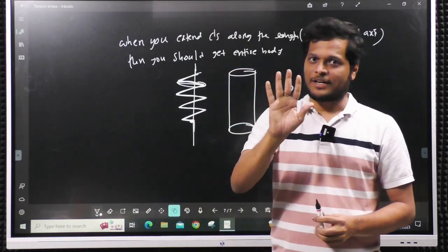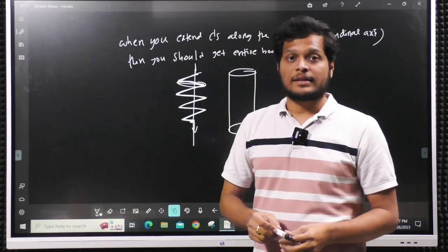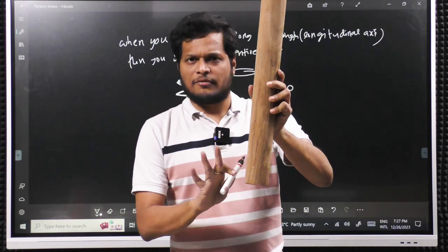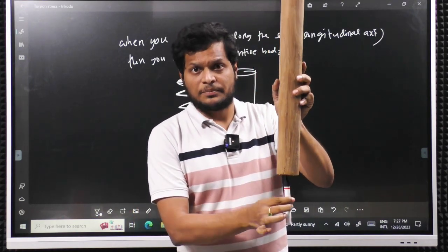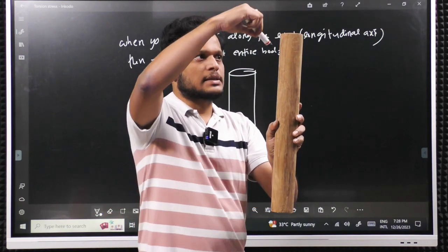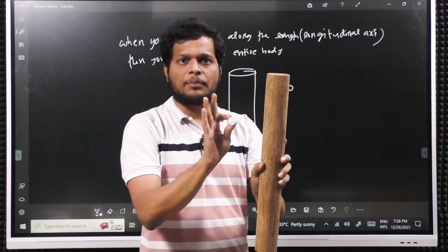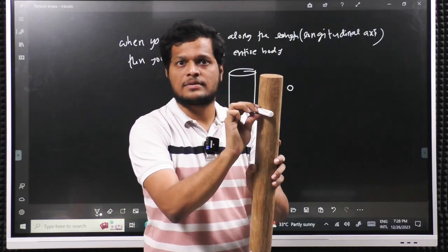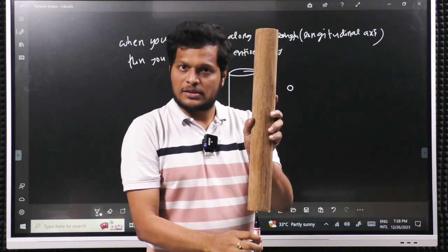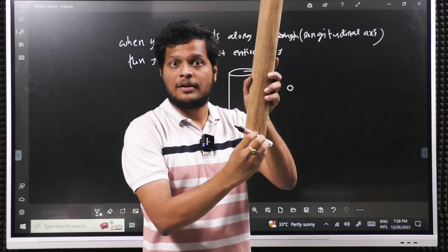Okay, now you got what is the cross section of spring, right? So for the cross section of spring, you are applying a load somewhere at the center in 3D. Just for understanding, imagine this is a spring, even though it is a circle, and you are applying a load here, at the center. So when you are applying the load at the center and this is your longitudinal axis at this point, this longitudinal axis is not meeting the load line, because the load line is at the center, not parallel. Obviously it creates torsion.